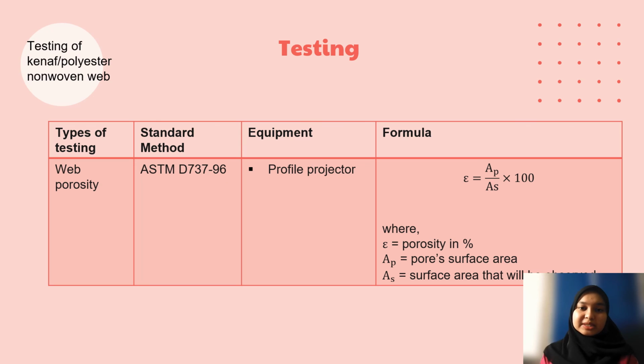This testing will be done using a profile projector to read the sample pore size under the lens. This testing refers to the ASTM D737 standard method, and the porosity will be calculated using the equation.